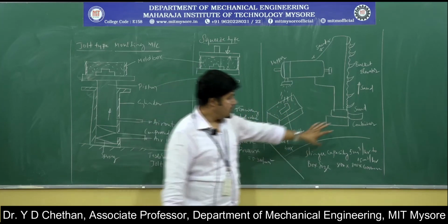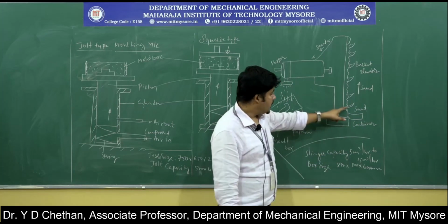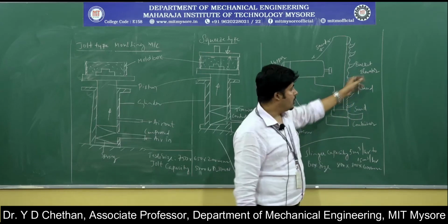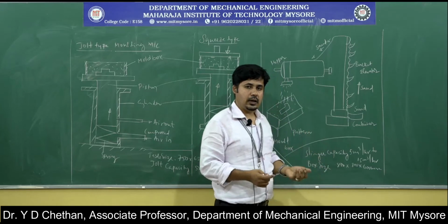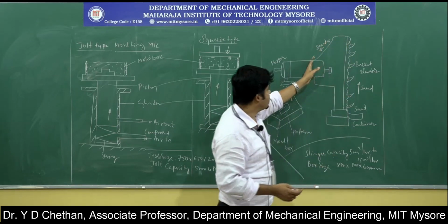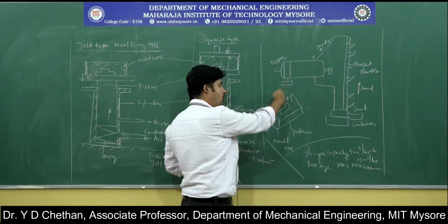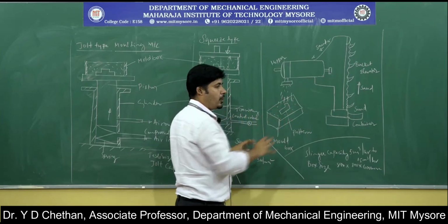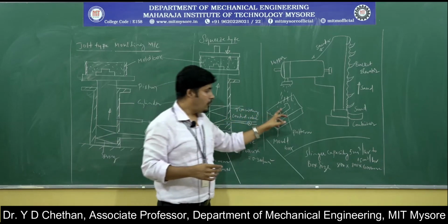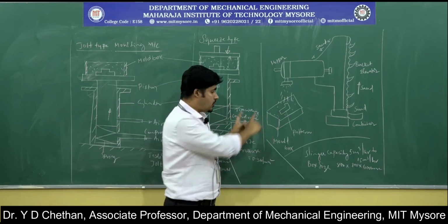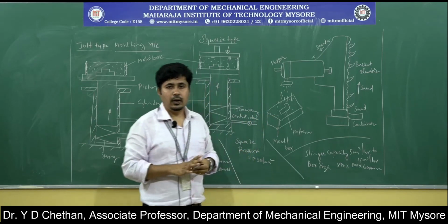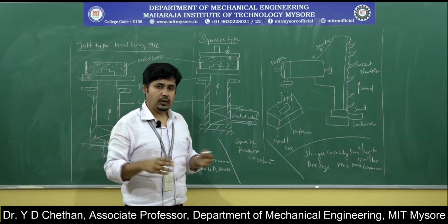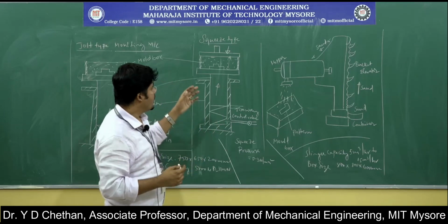That is the intention. Here this is the sand container with appropriate ingredients. It has a pulley and drive, and a rope connected with buckets that take out the sand and its ingredients, which are elevated to some level and then pushed into the hopper. From the hopper, with higher velocity, it feeds the sand ingredients, and that leads to perfect compacting of the sand on the pattern. Once you remove the pattern from the mold box, that leaves a good quality cavity, which can be used for the casting process. That is the concept of the sand slinger machine.